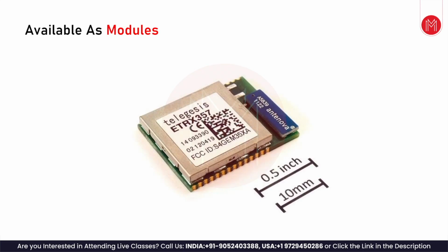Again, the same way, there may be an external antenna. This is a chip antenna, and this is the stamp module where the half cut holes are there. These can be soldered onto the pads of the main board, so it piggybacks onto the main board.